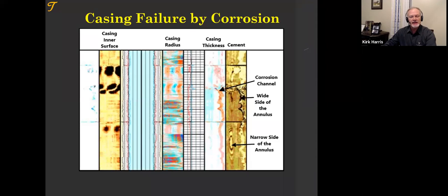It appears the casing, doesn't it? Now, I don't know, we may have corroded some of the cement, but this goes to just confirm even more. If the cement doesn't corrode, but I don't have good bonding and I corrode the casing, I still have a channel. The bonding is critically important. It's interesting as you look at steel corrosion versus cement corrosion, that really can be about the same, only maybe steel occurs slower but more consistently over time.